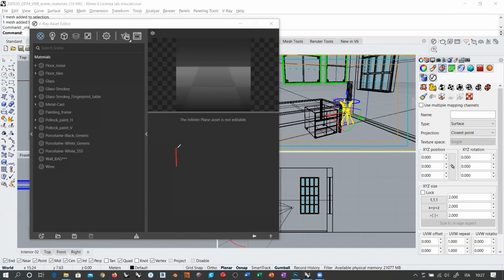So imagine that you have this simple geometry here, like a cube. Triplanar texturing allows you to project onto this object 3 different textures from 3 different directions. So let's say you want to apply one texture in the X direction, another texture from the Y direction, and another texture in the Z direction.